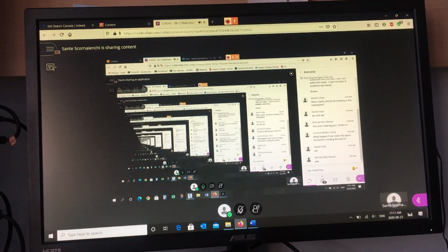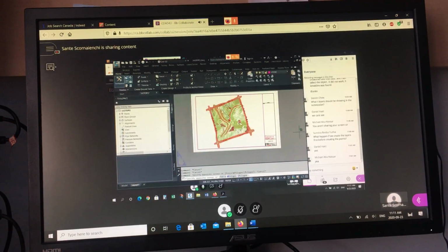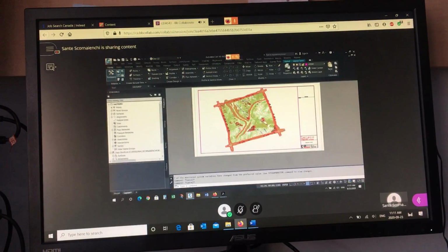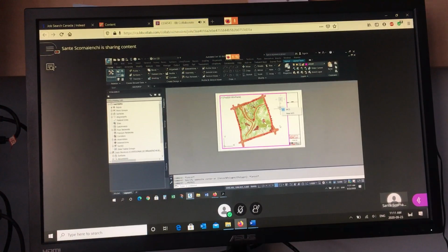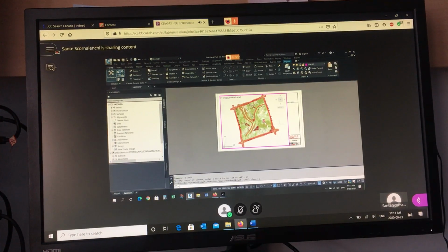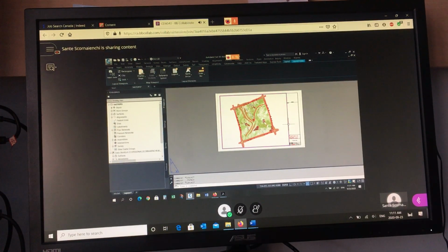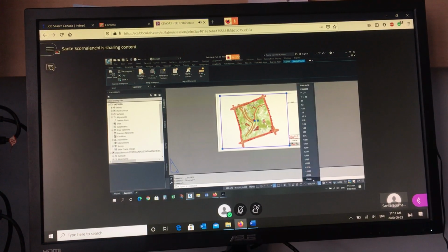And again, if you want to establish scale, when you create this, it always zooms extents. Okay, so if I go into here, if you look at that, when you first create it, it's got a weird scale. It wants to be 0.5. It has to be exactly 0.5, which is half of 1,000, 2,000. So I'm going to choose 2,000. Okay, so that's a true scale of 2,000.